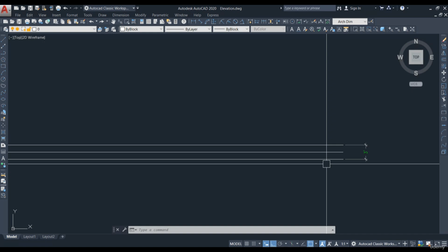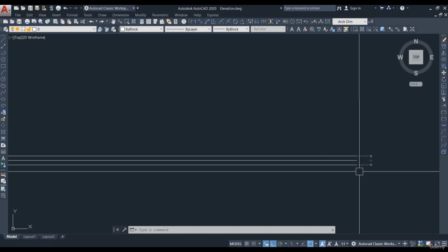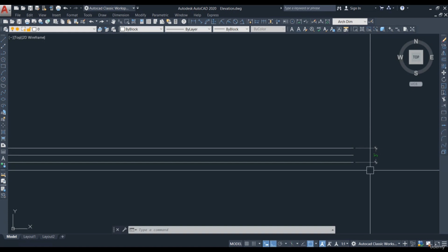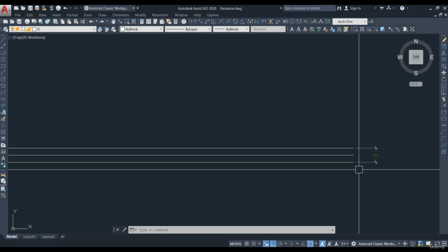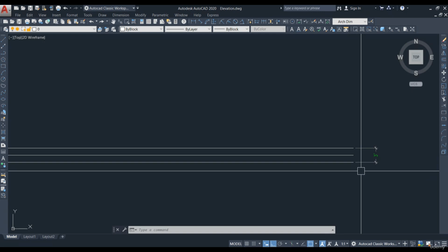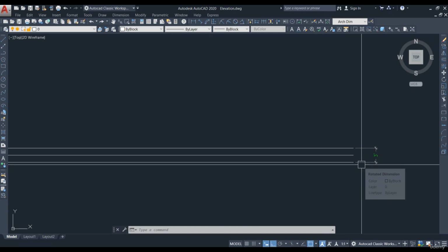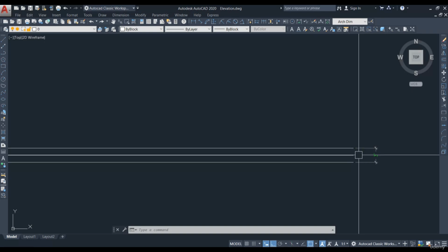This is very important. This we have already discussed in the previous lecture as well. It is mandatory to keep a minimum distance of 3 feet from the road level to avoid the water seepage problem when the heavy rain comes or any drainage problem is there. This will help to prevent the seepage of water to the house.